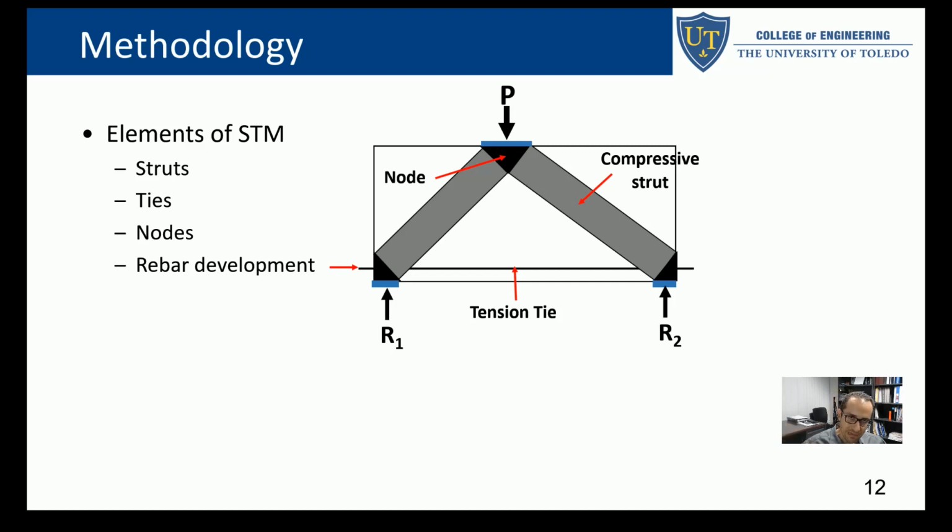So the reinforcement development is not something super critical in the sectional method, especially at the supports. In a simply supported beam situation, you don't really care much about rebar development at the supports. In fact, we just cut it at the support because the moment is zero, right? At the support, rebar is not needed. That's not true for deep beam action. So the stress is uniform, and you've got the stress in this situation the same at the support as at the midspan.